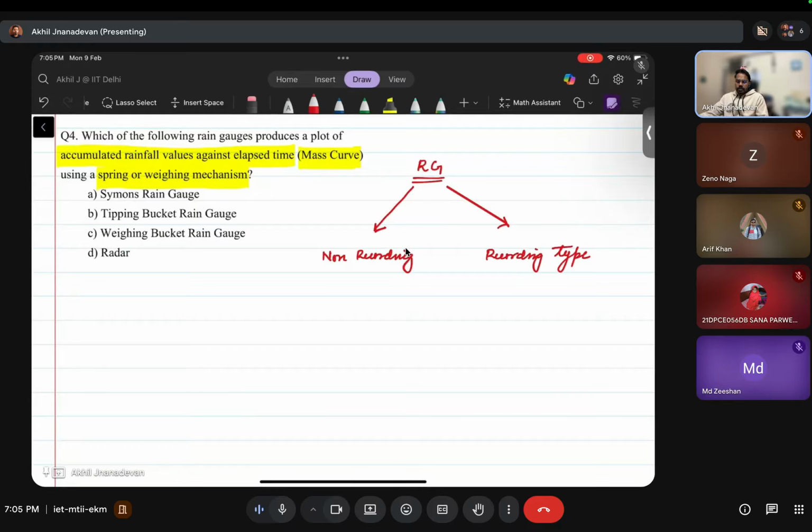So these instruments are kept, and they will be measuring rainfall in terms of depth of water collected by a particular bucket or instrument, but they are not recording. We have to take and see, or weigh and see, or see the level and measure the rainfall that happened. That is called non-recording type. This was used extensively in earlier times.